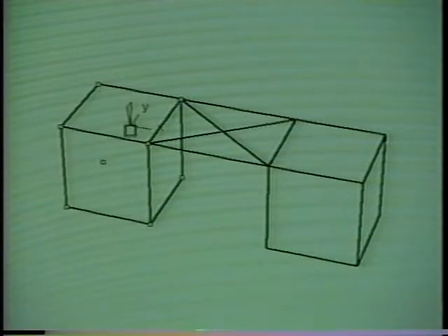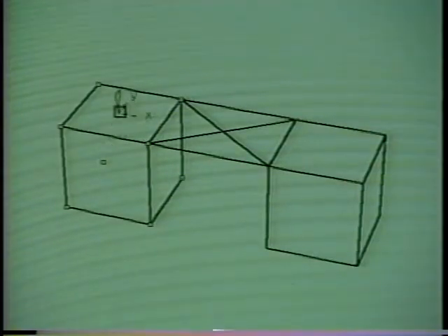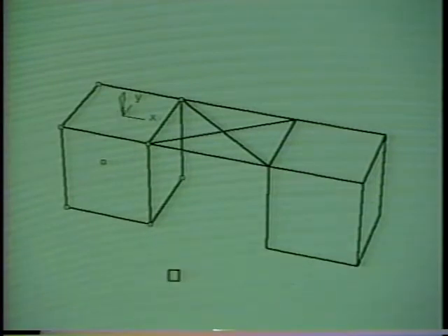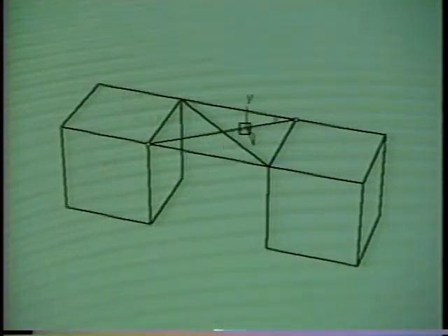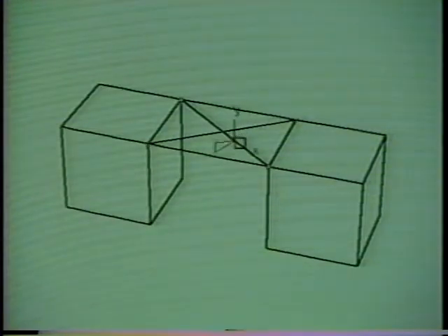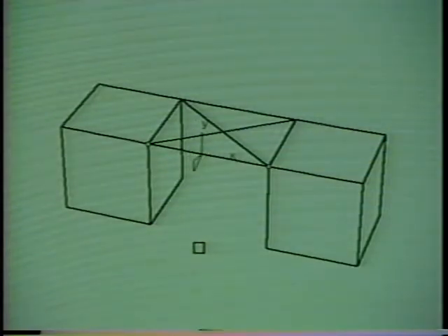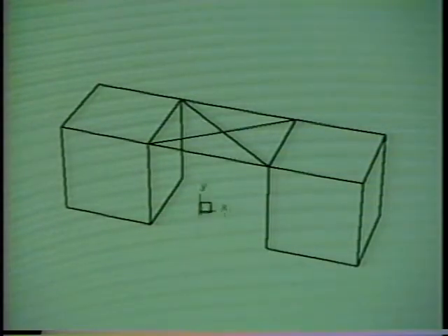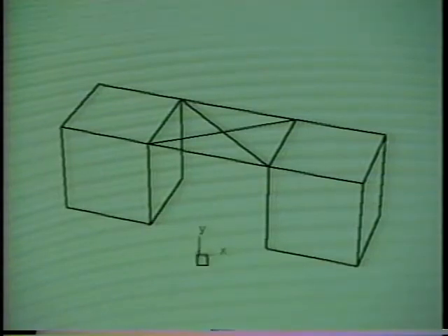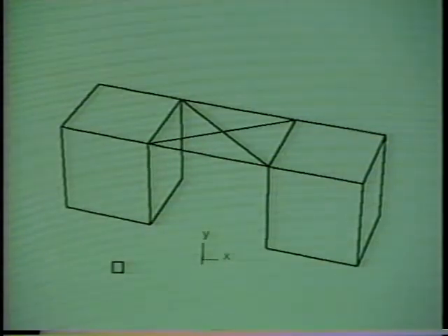When the cursor passes over the cube, gravity snaps the skitter to the nearest cube face and orients its z-axis to be perpendicular to the surface. When the cursor passes near a line, the skitter snaps to the line's nearest point and the x-axis of the skitter becomes parallel to the line at that point. When no objects appear near the cursor, the skitter snaps to an invisible plane parallel to the screen.